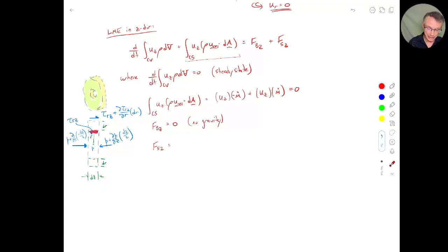So if the shear stress on the inner face, that's this inner orange bit, is tau rz, then when I go to the outer surface, it'll be what I started with plus how that stress has changed as I've moved in the radial direction times how far I've moved to get in the radial direction. That distance is dr. Okay, so hopefully you understand that. And again, the sign convention or the nomenclature for shear stresses is this is the stress on the radial face in the z direction. Okay? And both of these are positively drawn shear stresses. So those are my surface force terms.